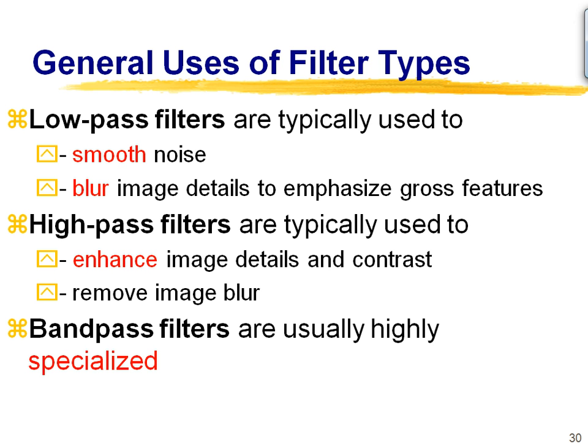Because if I truly have a nice contrast, like a step signal in my image, it's going to make this guy look like that, because it's going to remove high frequencies, the spike here, and it will appear as if it's smoothed out. It's going to blur. So that's what a low pass filter will do for us.